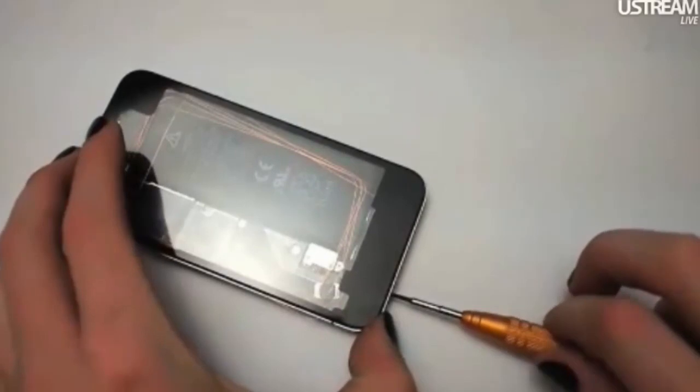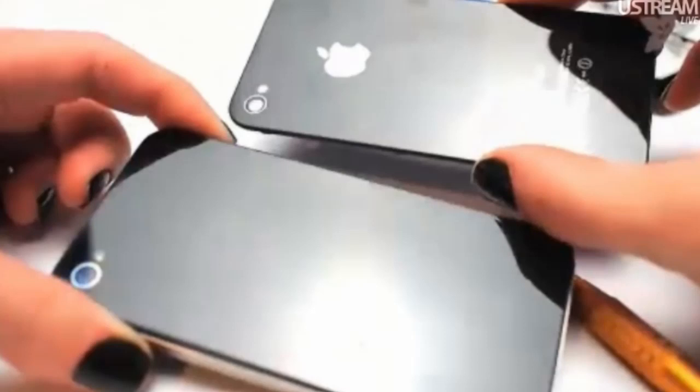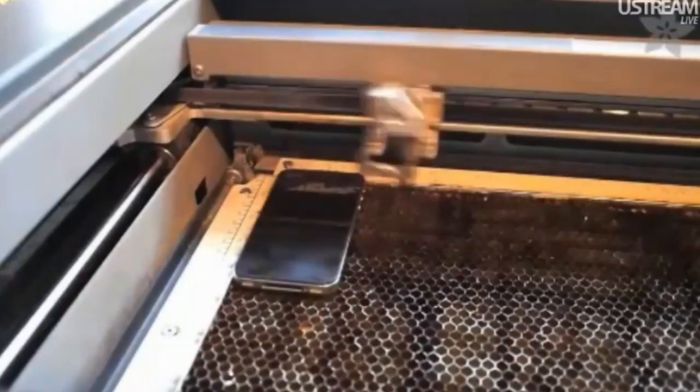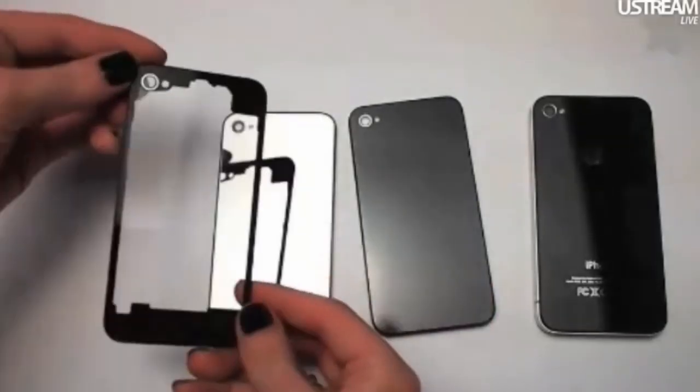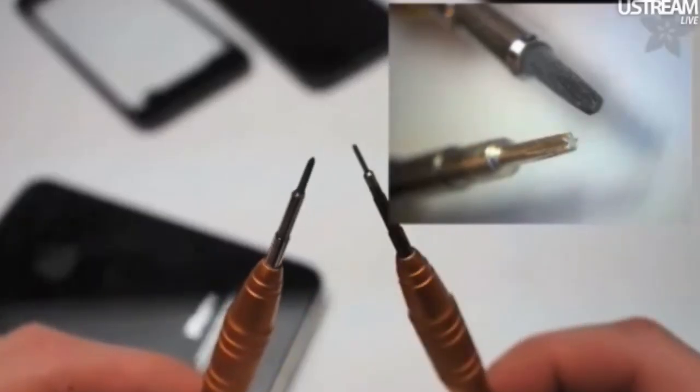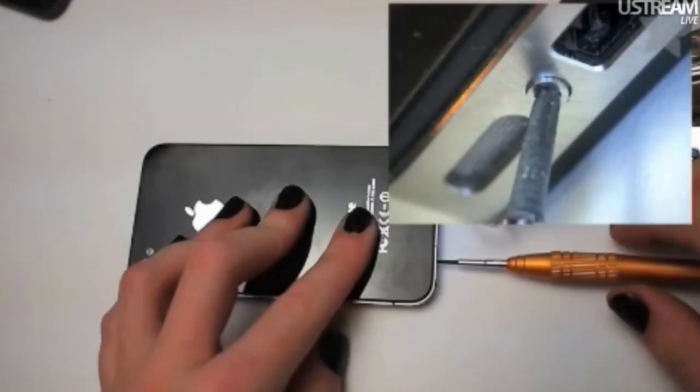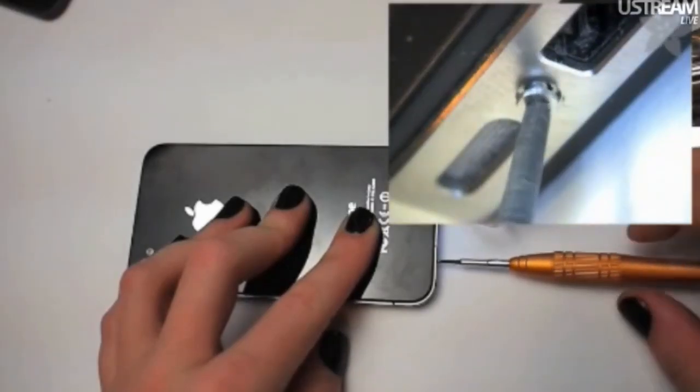It's really easy to change the back plate on your iPhone 4 or 4S, and today I'm going to show you how. There's 2 screws on the bottom of the phone. Just unscrew those. They're either Phillips or Pentalobe. Then slide the back plate up and tilt it off. You can replace it with a plain black plate, suitable for laser etching, a clear plate so that you can see all the inner workings of your iPhone, or a mirrored plate. Comes in handy when you want to see if you have something in your teeth. We also carry both screwdrivers you might need for this mod, and the USB microscope can give us a nice close-up of it in action.